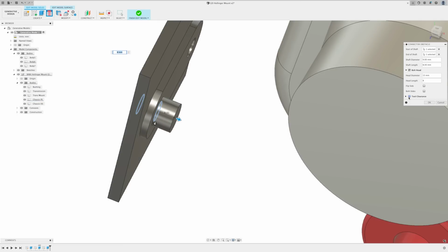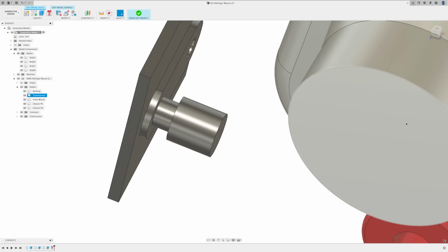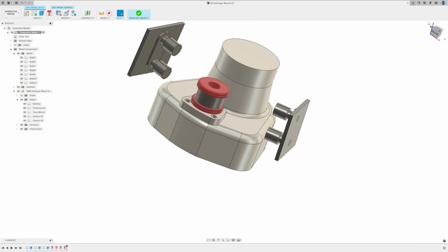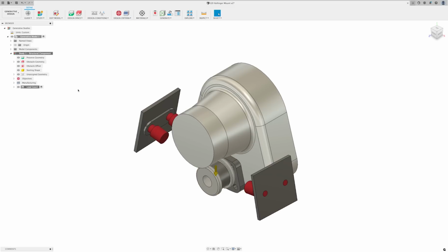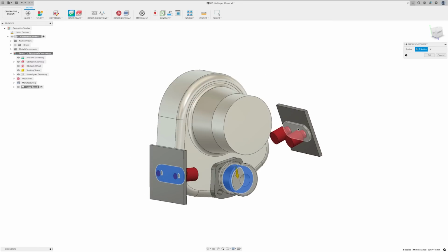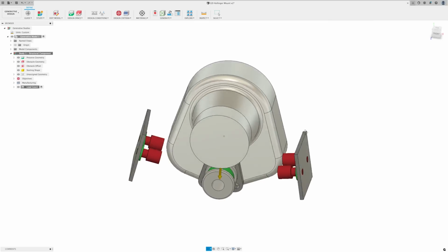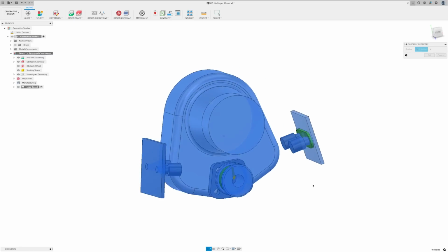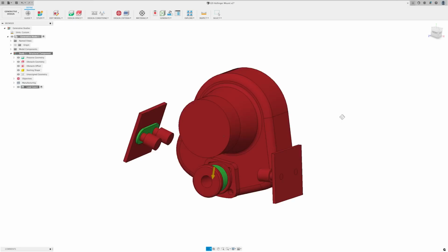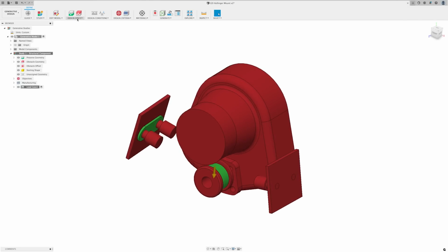We also have the tool clearance preference. Using this will allow easy access to the hardware. Now we have 4 more bodies for the connectors that can be used for obstacle geometry. So let's finish editing the model, select the Preserve Geometry function, and select the solid bodies for the 2 plates and the sleeve around the bushing. These bodies will turn green. Then the same idea for the obstacle geometry, selecting the solid bodies for the connectors, chassis mounts, and the rear of the transmission, which will turn red.